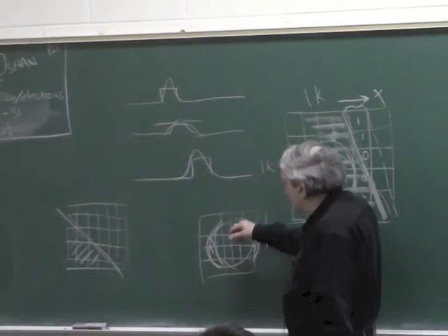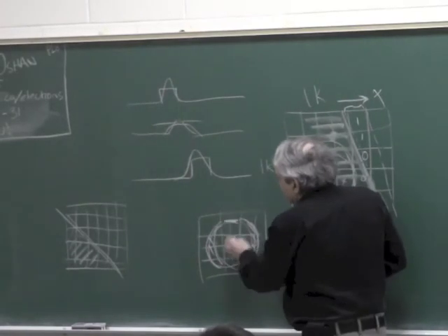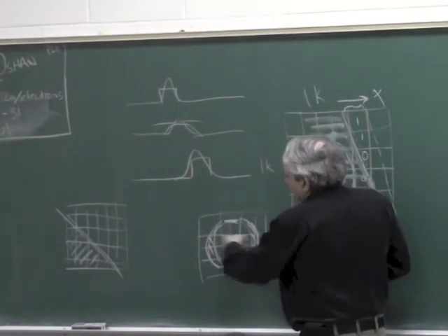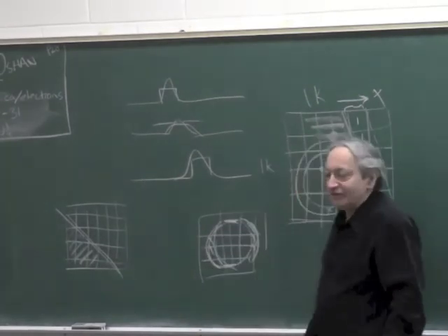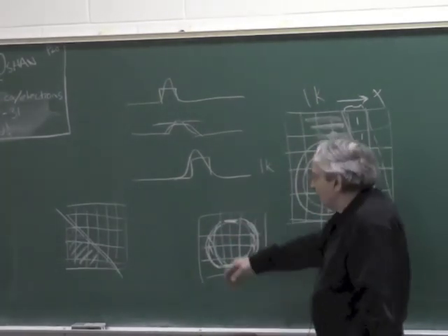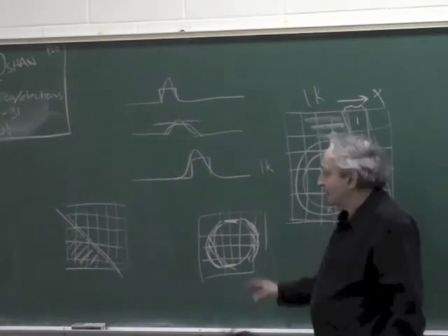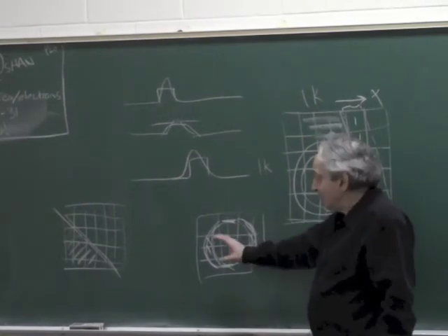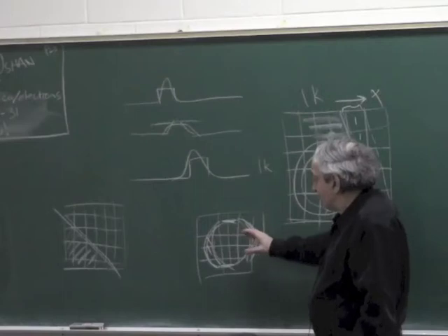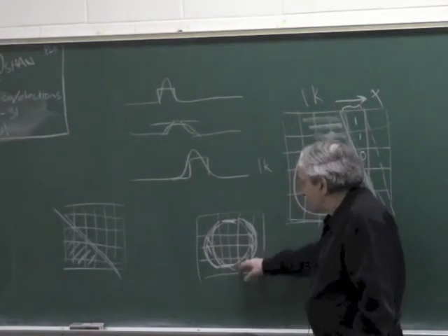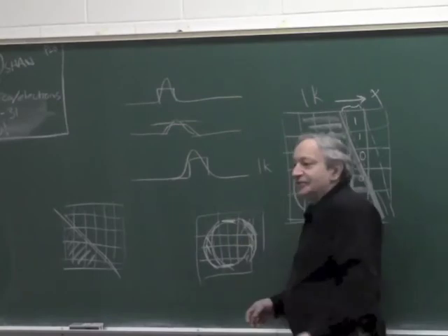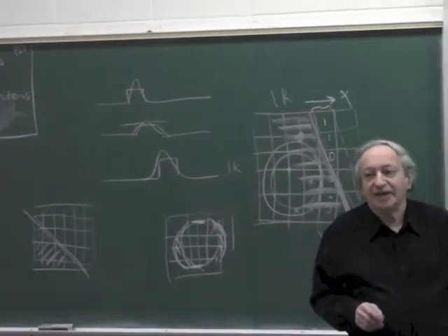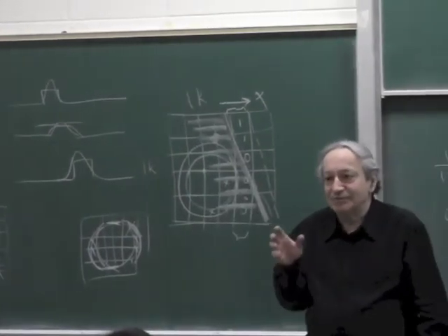Some pixels will be less effective, like these pixels here will be less effective if it moves this way, but you have a lot of other pixels. So if you have a circle which is maybe 250,000 or 500,000 pixels out of 1 million, any movement of 1 pixel will cause thousands and thousands of pixels to change states. So dust wouldn't matter, and you get very, very high accuracy from the slightest movement.